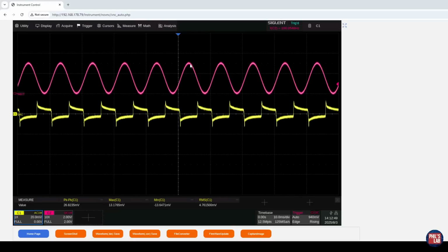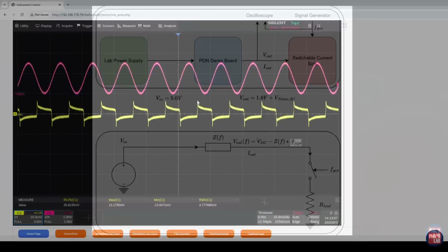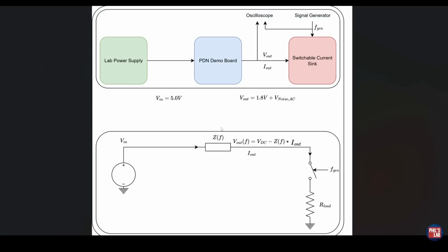Then once we disengage the load current, so we go from a peak high of our sine wave back to 0 when we're turning off the FET, the voltage of the output noise now overshoots the other way. And this is because, again, we have this series resistance, which is a frequency-dependent term. So at 100 Hertz, this series resistor has a particular value, and we still have that fixed load current value, and therefore we will get a voltage drop as the load current demand changes.